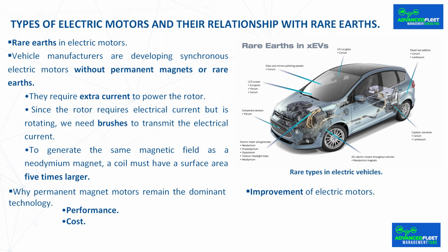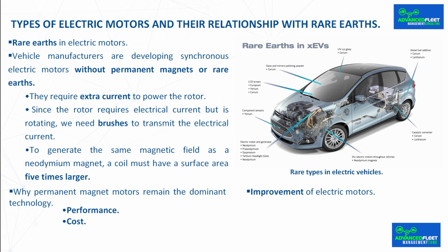This term refers to the intrinsic ability of a material to preserve its magnetic properties even with significant increases in temperature. While it is easy to not exceed a magnet's critical temperature limit and cause it to permanently lose its properties, maintaining those properties at all times is a more complex task. Increasing the coercivity of neodymium magnets is achieved by incorporating additional rare earth elements such as terbium or dysprosium.